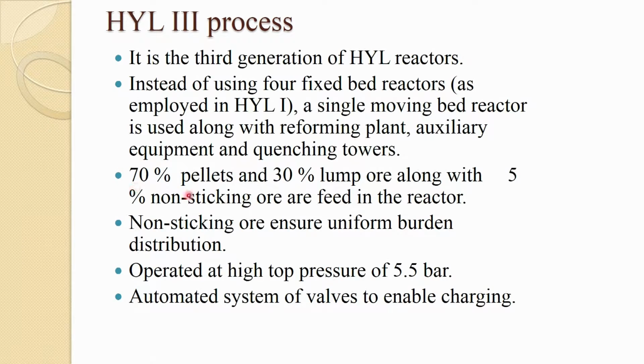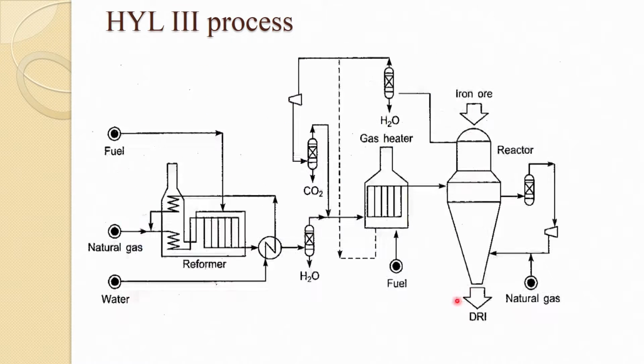So, 70% pellets and 30% lump ore along with 5% non-sticking ore are fed into the reactor. Non-sticking ore ensures uniform burden distribution. So, sticking does not occur. Operated at high top pressure up to 5 bar, automated system of valves enable the charging.